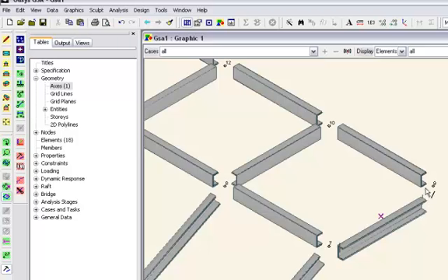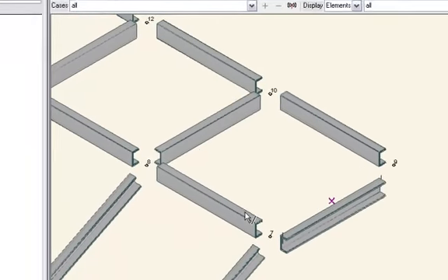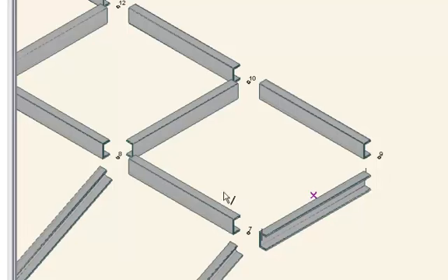It's best not to offset everything. I mean, if you just do a simple steel frame, we wouldn't recommend offsetting all the beams down, because it can increase the floor stiffness if you're not careful.